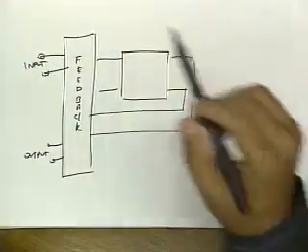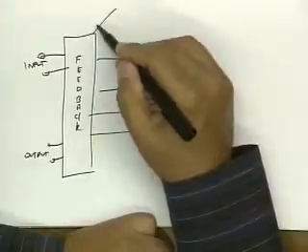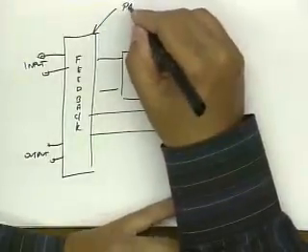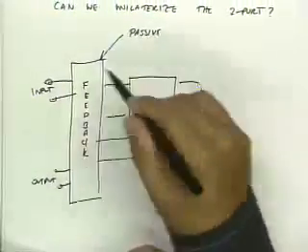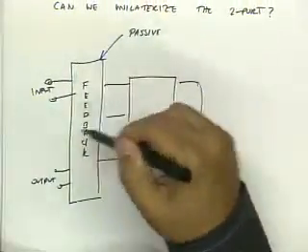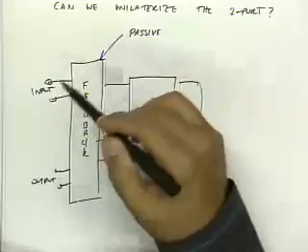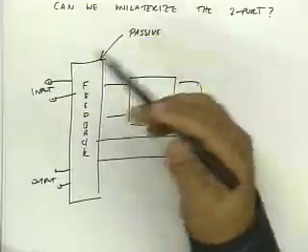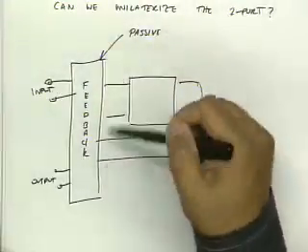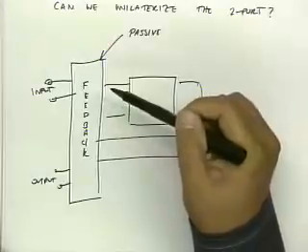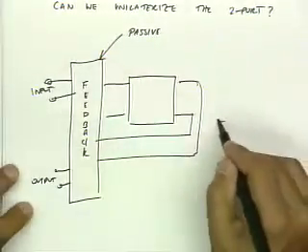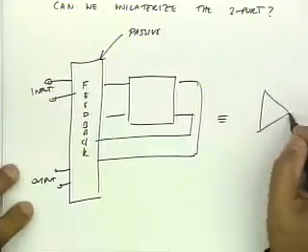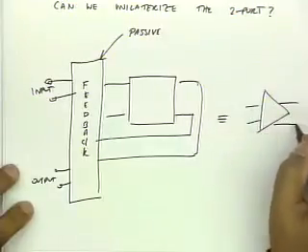Okay? So if I'm willing, this is basically passive. In other words, I'm not going to be putting any amplifiers in here. I'm just going to be putting L's, R's, C's, maybe transformers, but whatever I put in here is still passive. And the idea is that I want to create a new 2-port, so this is now equivalent to a new 2-port, which is unilateral.